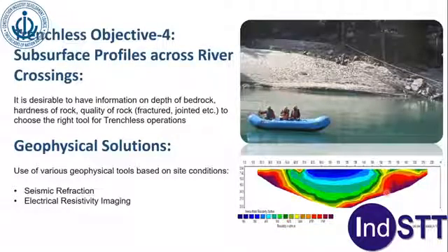Another example of greater depth, 880 to around 800, so 80 meters depth. It was for a hydropower project. Again you can see rock interface clearly. Here. This is how the model looks. Again, it's 1080 to 1050, 30 meters of depth. This is a distance of around 115 meters. You are able to see how the rock is behaving.